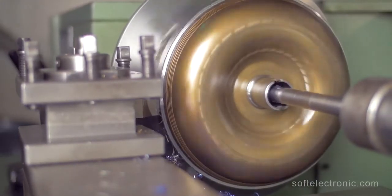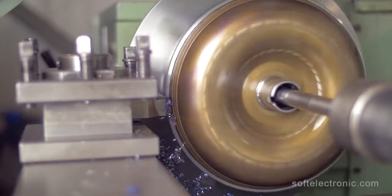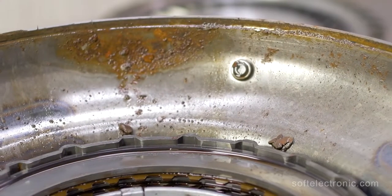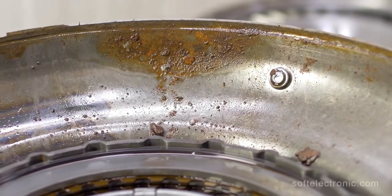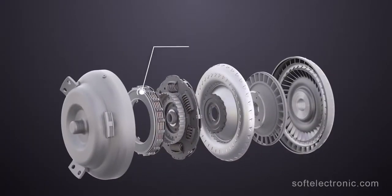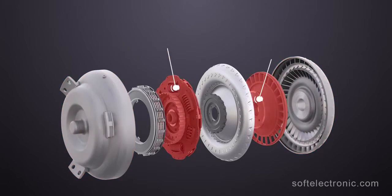This is followed by a careful separation of the torque converter housings and cleaning of the welding areas. The disassembly of the torque converter continues. In the case of metal shavings, it's necessary to thoroughly check the automatic gearbox and find out the reason for their occurrence. Causes for a problem in the torque converter may be incorrect engagement of the friction mechanisms, imbalance of the torque converter housing or some of its components, damage or disassembly of some elements during operation.